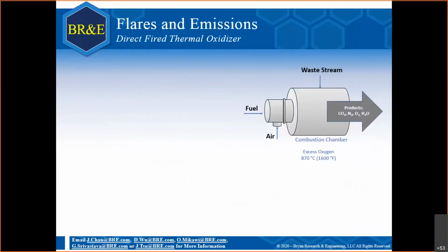Let's move on to discuss a little bit about the setup of the incinerator or the thermal oxidizer. These terms are used interchangeably. The thermal oxidizer is very basic in design. It consists of a burner and a combustion chamber, as you can see in the picture on the right. Its purpose is to convert the combustible components, such as your VOCs, to less harmful species through the use of heat. In this example, we have your propane being oxidized to form your carbon dioxide and your water. We have the air to provide the source of oxygen. A complete combustion will yield water and carbon dioxide.